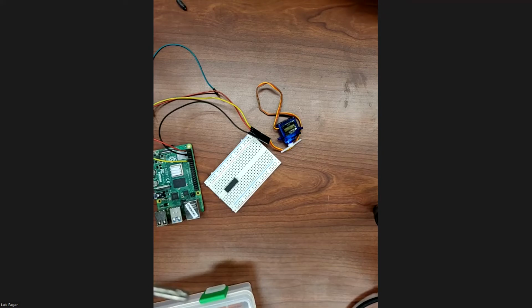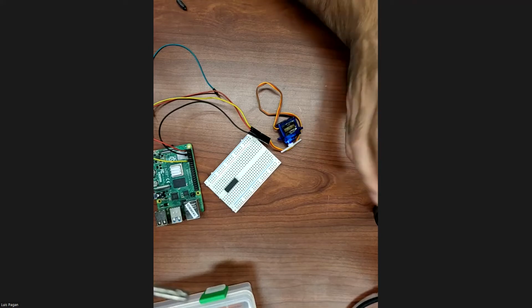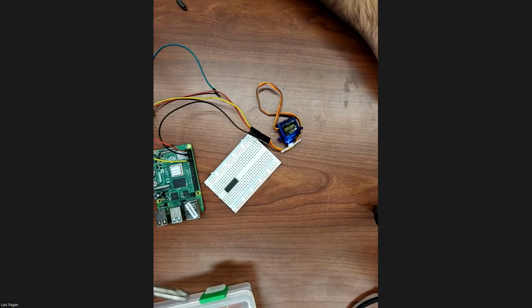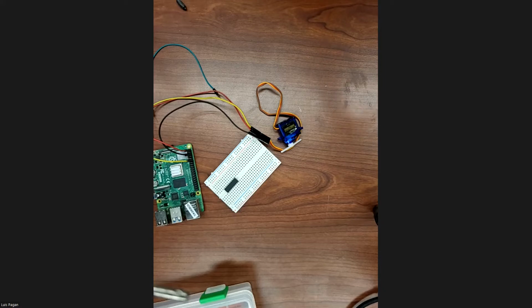But let's say you have a combination of motors and servos. The maximum you could get is 4 motors, assuming that they're grouped into twos. So let's say you have motors on this side and motors on the other side, and you need turning or steering. You can control these two to set them to the same speed, because it doesn't make sense to set them at different speeds. So these will stay the same speed, and these can be set to a different speed or different direction, depending on whatever it is you want to do.